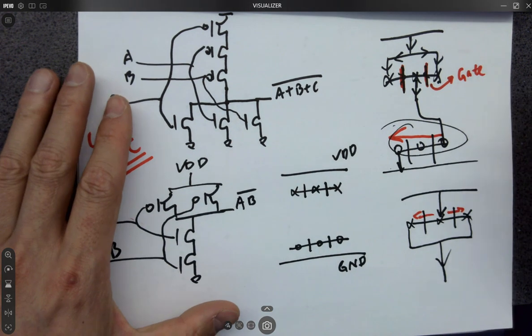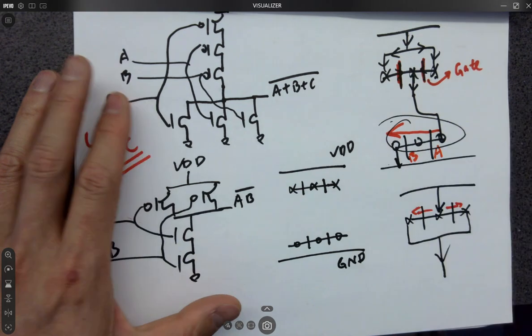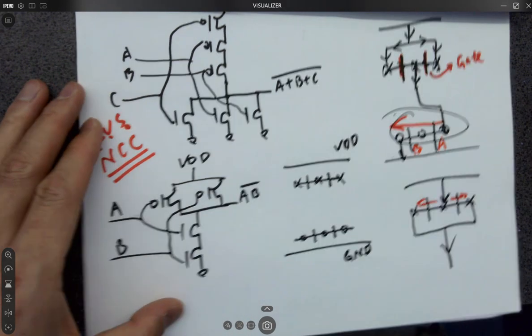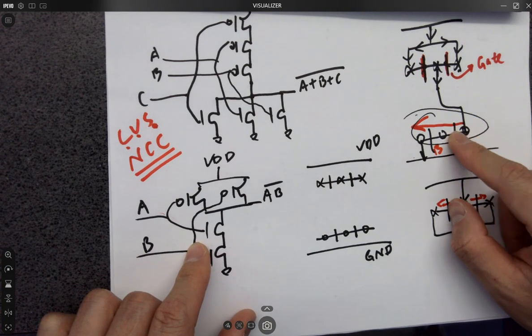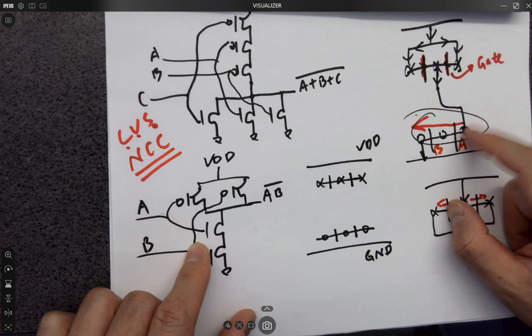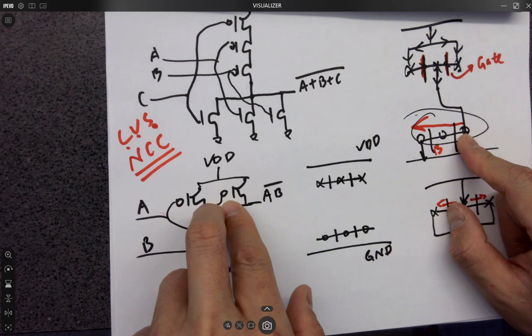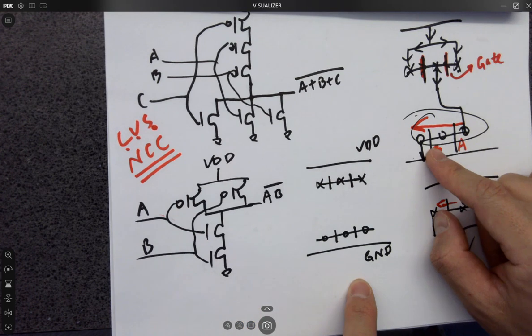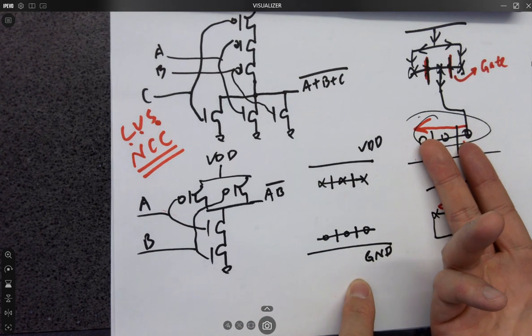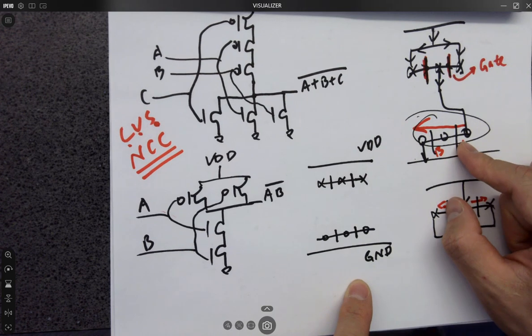But which one do we want? For example, if this is A, this is B. You can see the position here. When the wire comes down from the PMOS, firstly it reaches transistor A. Same thing when the two parallel get merged over here, firstly it reaches NMOS A, and then B. So this must be A, this must be B. If you swap them, you're not passing LVS. Makes sense, right? So this has to be A.